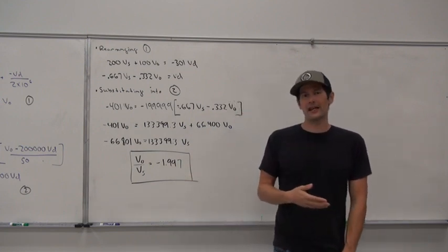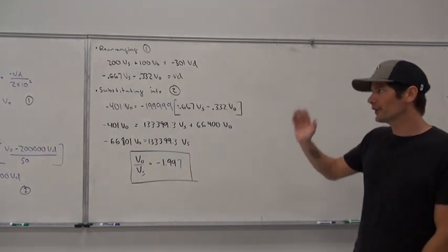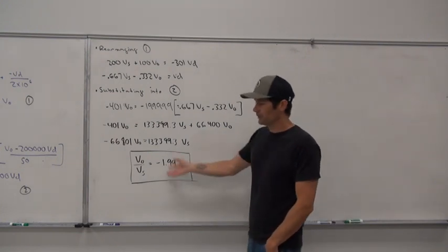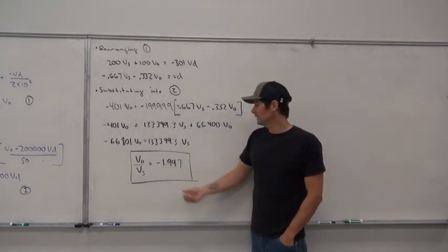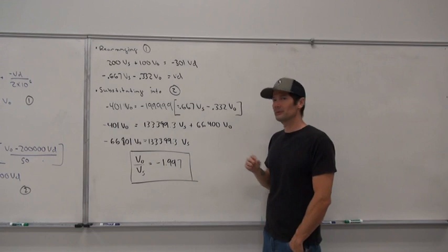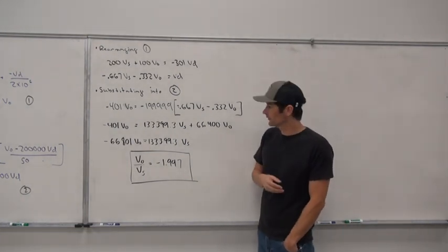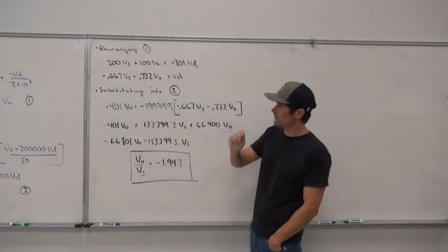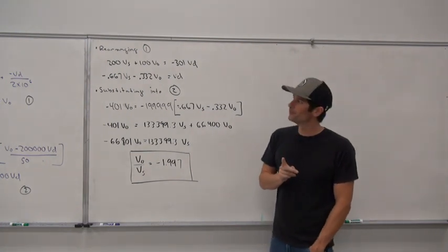And so that means that if we had 10 volts on the input, the output is actually going to have a gain of negative 2, or come out to be basically negative 20 volts. So it inverts that polarity because we connected that to the negative terminal.